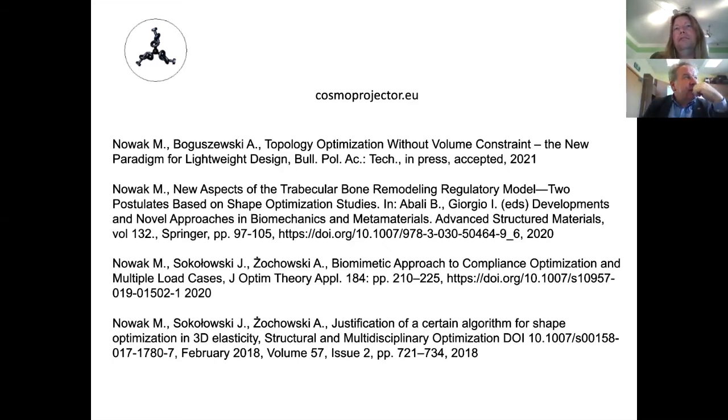And we produced a completely different approach, because in our code the finite element method is just used to compute the distribution of the strain energy density. So we just produce our own mesh, and we don't evolve the mesh. Every step is a new mesh. This is a little bit not so convenient, but what is convenient is that there is no problem with the element evolution.